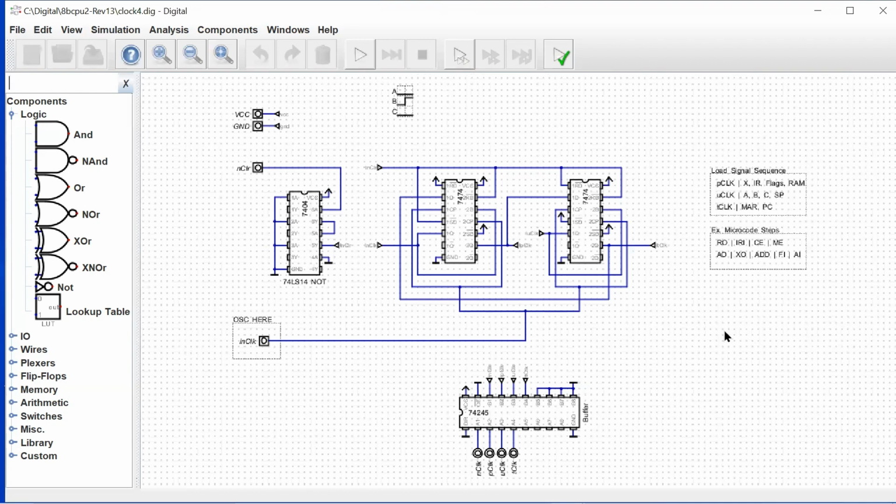I just eliminated all that stuff because in practice we're not going to do that. We're always going to be in running mode, running on the high speed oscillator. So in our final hardware, we're just going to have our high speed oscillator. And all that extra circuitry is gone, and it's greatly simplified, certainly the clock design.